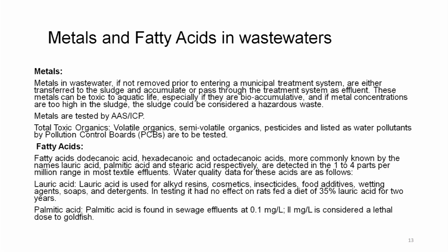So, metals have to be analyzed, and we saw a list of metals, and we also saw that total metal content cannot exceed more than 0.37 milligram per liter in any wastewater that is permissible to be let out. Metals are tested by atomic absorption spectrometer, that is AAS, or inductively coupled plasma spectrometer.